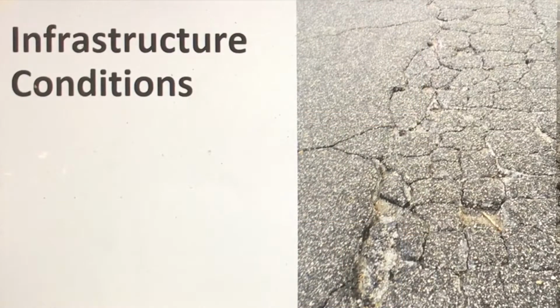The existing infrastructure conditions were identified during the second site visit. The existing roadway design was a flexible pavement design. Photos highlighting the various defects of the road segment were obtained for further investigations. One of the main issues identified was longitudinal and transverse cracking up to 2 inches wide along the entire roadway section, as seen in the picture.